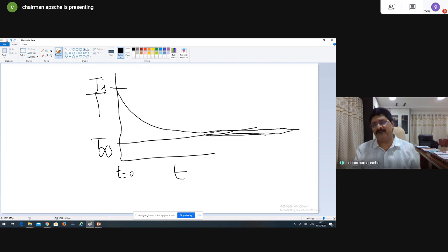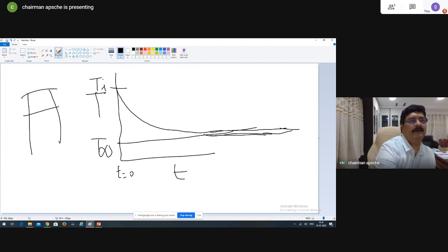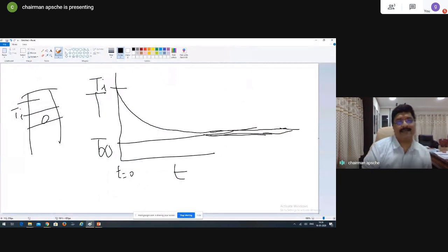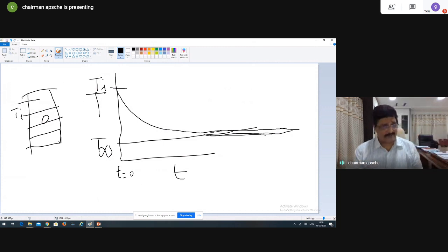How much time does a stroke take? Only a few milliseconds, not more than that. So every time the temperature is changing, your thermocouple has an initial temperature Ti. What do I mean by initial temperature? Now when your piston and cylinder are here, it has one temperature, let me say Ti. Now the piston has changed, and the thermocouple is now exposed to a new environmental temperature T infinity, because the piston is displaced and the temperature varies. So immediately it should adapt to the environment temperature.